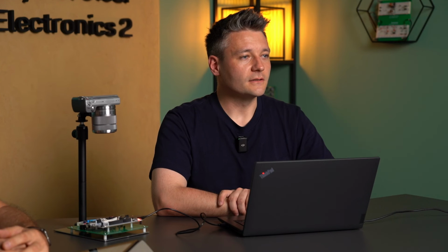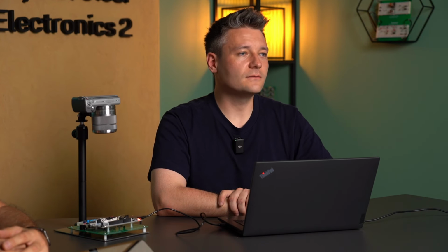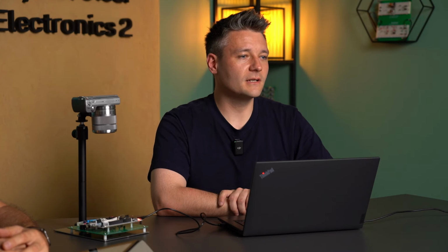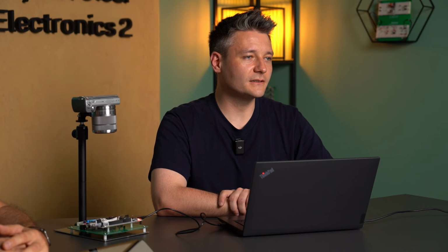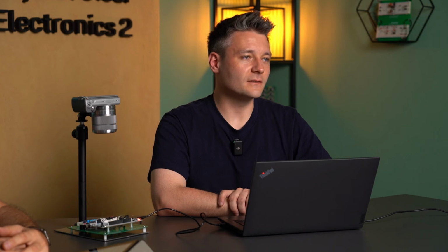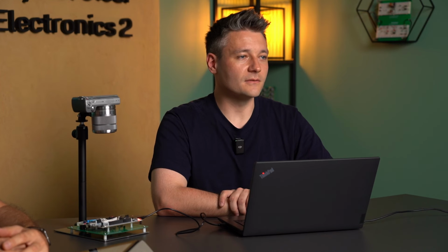That being said, let's talk a little about the different forms that RTC can take in each system. For example, in an older microcontroller, there was no hardware unit dedicated to the RTC task, so in one of my previous projects, I found the best solution was to add an RTC IC communicating via an I2C bus to the microcontroller. One such example is the DS1307 integrated circuit mentioned in the curriculum. In this case, the IC did the accurate timing, and I could retrieve the information I needed via the I2C.